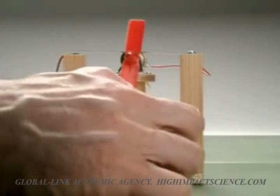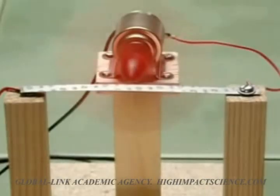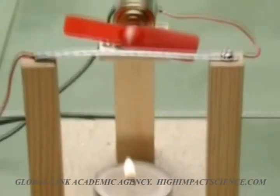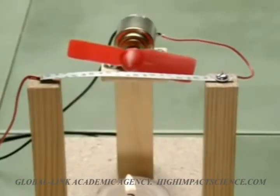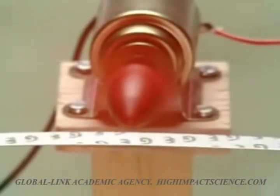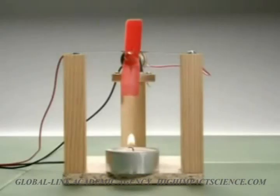Look here. A candle is placed under a bimetallic strip. Can you tell what is happening? The bimetallic strip is working as a switch. Heat from the candle causes the strip to bend downwards. This completes the circuit, supplying power to the motor. The fan then rotates, cooling the strip, which then bends upwards, breaking the circuit, and so on.